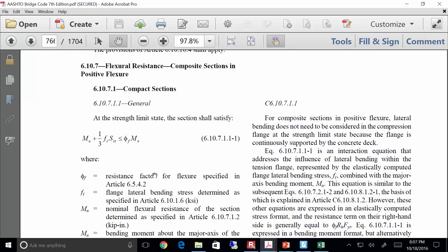Simple, right? Now, we've got this term related to lateral flange bending. Again, right now we're not going to consider wind effects. We can consider that later, but right now I'm really not worried about it, and you're going to see it really wouldn't significantly matter anyways. I think you can guess when you see the numbers. But Mu has to be less than or equal to phi Mn. Now, one of the nice things about the spec and the way it's been calibrated, phi for bending and for shear is 1. Okay? So it's simple. If you remember in steel design for bending, phi was like 0.9. Nope. Phi's 1 for the bridge spec, so it's a little easier.